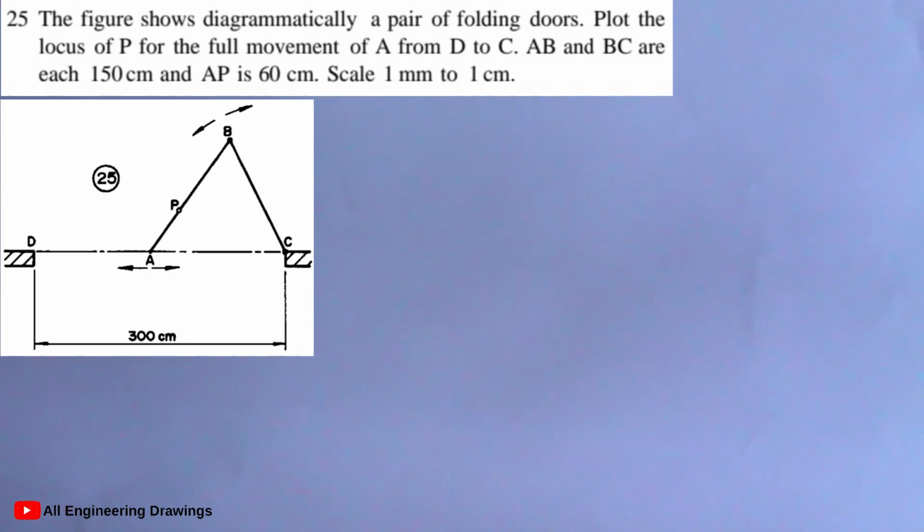Scale 1 millimeter to 1 centimeter. So the question says scale 1 millimeter to 1 centimeter. What it means is that any dimension you see in centimeter, you just use it as millimeter. So we'll start the question by drawing line DC.